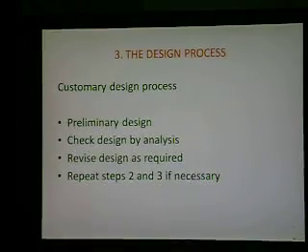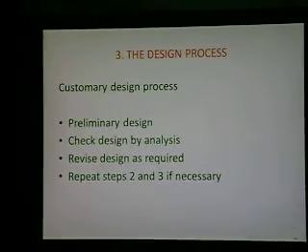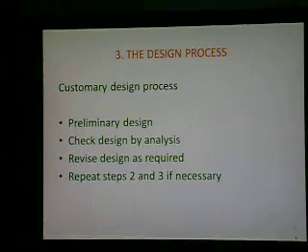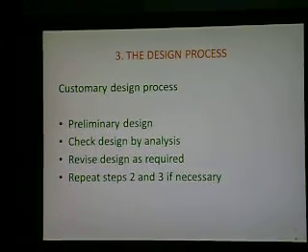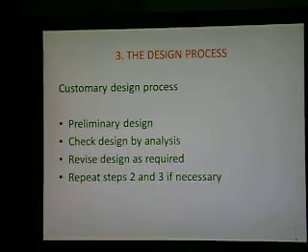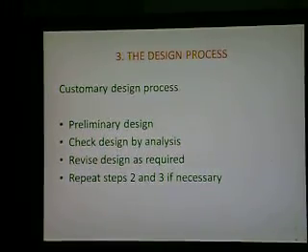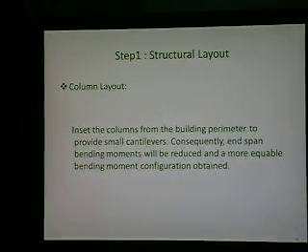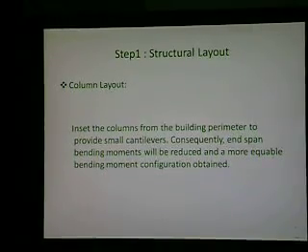The design process. Generally, a design process consists of 4 steps. Preliminary design. Check the design by analysis. Revise the design if the obtained values exceed the limited values. Repeat steps 2 and 3 until you get a favorable design. Step 1. Structural layout. Column layout means positioning the columns according to the distribution